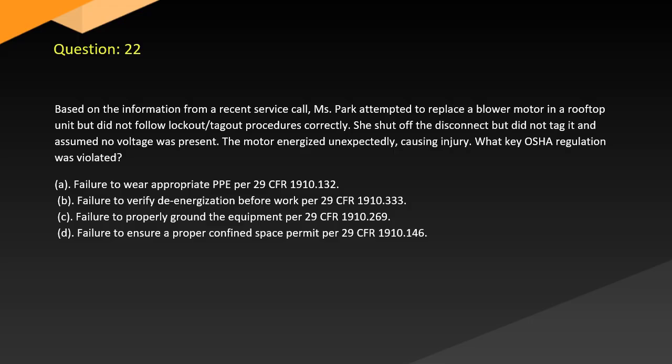A. Failure to wear appropriate PPE per 29 CFR 1910.132. B. Failure to verify de-energization before work per 29 CFR 1910.333. C. Failure to properly ground the equipment per 29 CFR 1910.269. D. Failure to ensure a proper confined space permit per 29 CFR 1910.146.